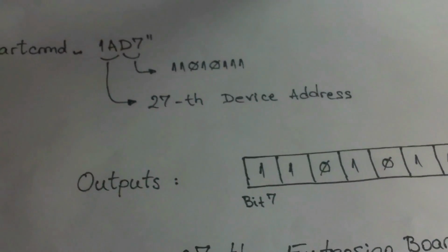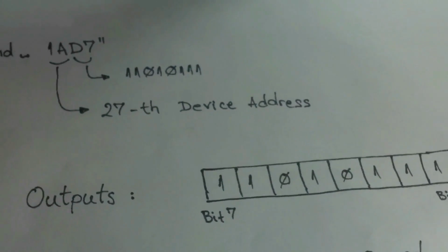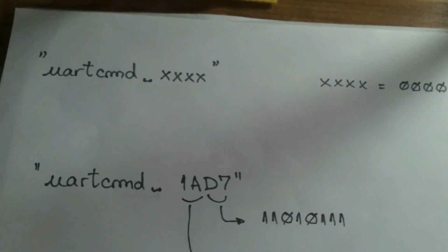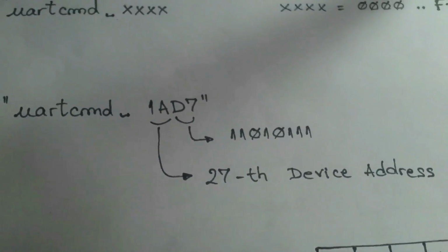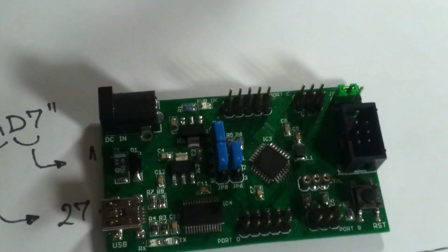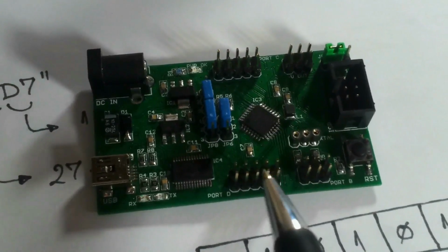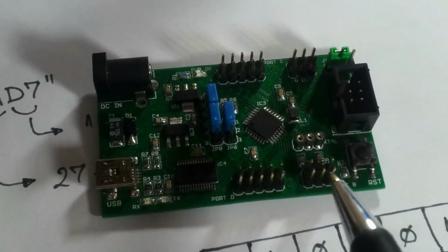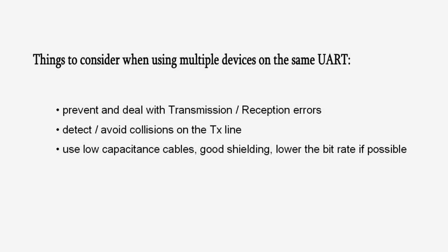And there's a lot of stuff you can do. You can serialize the software for these boards, use jumpers to implement hardware addressing. 8 bits are enough to generate 256 different addresses. Here's a small AVR platform I made a few years ago. I could use this whole port for address and this other one for the outputs, and I still have 6 pins for the inputs.